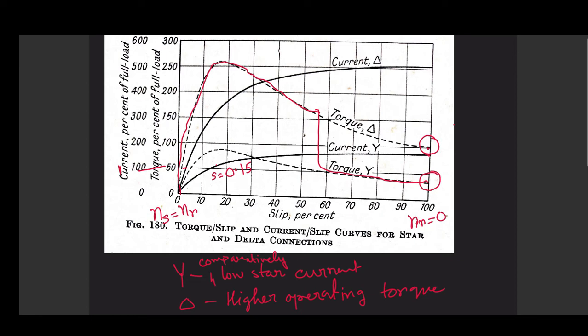But what I want to mention is that in case of a machine that employs a squirrel cage induction machine, we generally try to reduce, or try to apply minimum amount of load during start. So once we can reduce this amount of load, then what would happen?